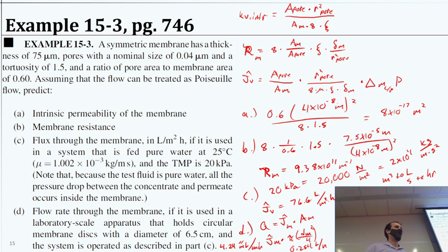And right, so there's different ways to relate it. You can do the flux if you're keeping the pressure constant, or you can monitor the pressure increasing if you're keeping the flux constant. It's harder to do constant flux, but you can do it with flow meters and stuff. Constant flux is what is typically done in practice because we want a certain amount, so there are practical reasons we do that.